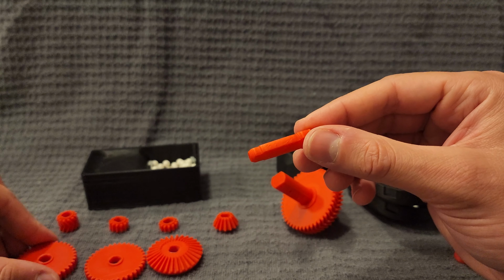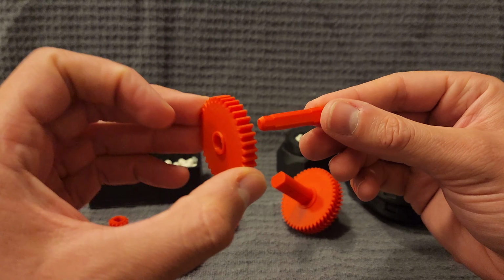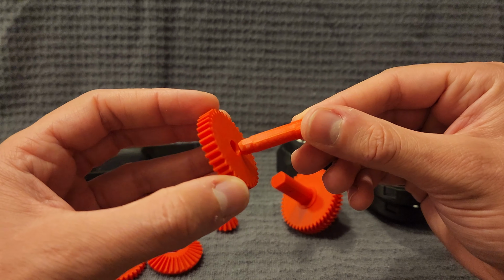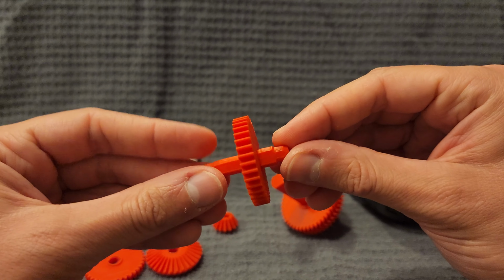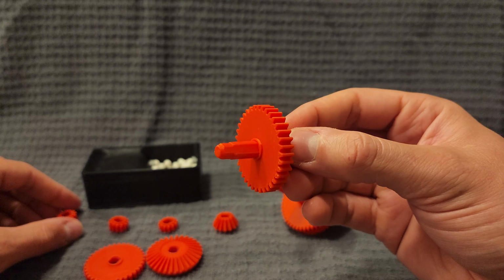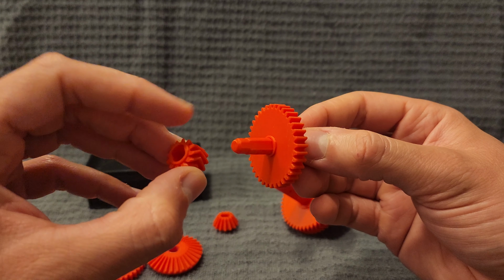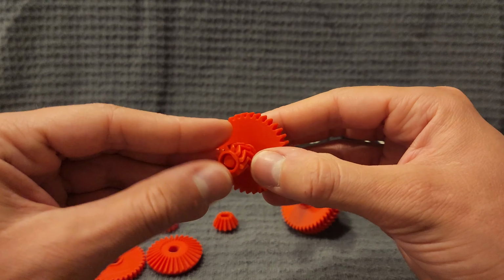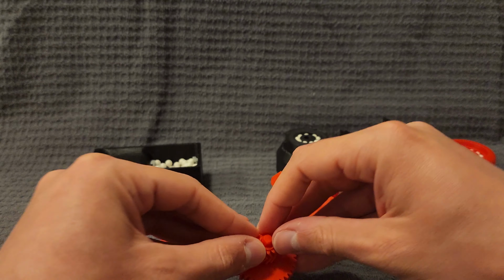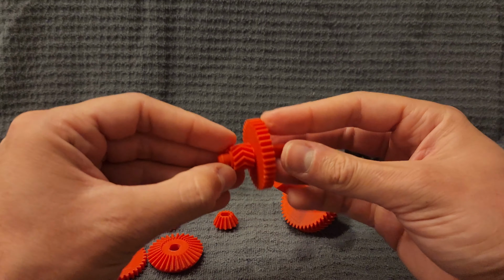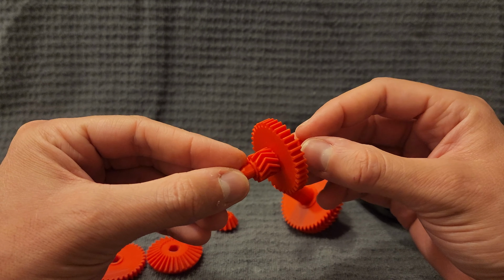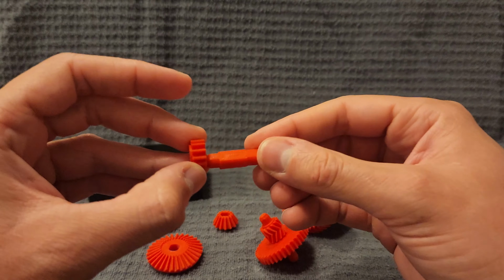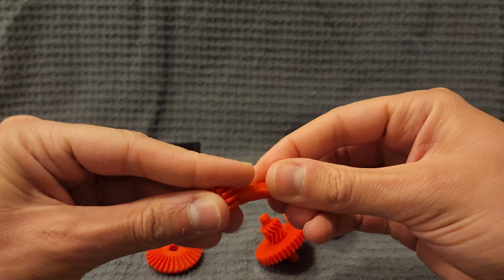The second one is going to be the one with the step that's on the thinnest ridge. And again, the bump has to be towards the end on which you enter the gear, as you can see here. We take the bigger spur gear, that's also the thickest one, and then you put the herringbone small spur gear next to it, again with the bump towards the end of the shaft. Those bumps are there to ensure that the gears don't rub against each other or against the case while you are using the device.